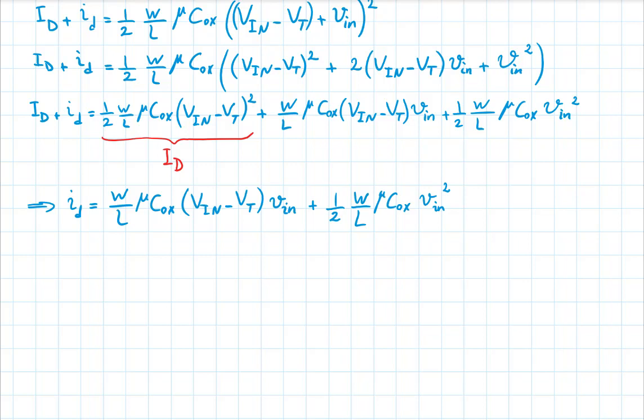Yeah. But that's exactly how you want to think. If Vn is really small, it's a small signal. So which term do I eliminate? Do I eliminate the first one? If I have a very small number, if I take its square, will it grow larger or smaller? Imagine Vn is a number much smaller than 1. If I take its square, will it grow larger or smaller? Smaller, right? So if you have a small quantity, neglect the quadratic term, the second order term.